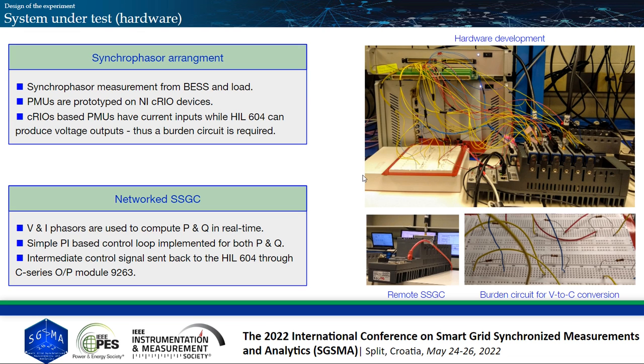So, we had synchrophasor measurement from PMUs, from battery energy storage system and the load. We had PMUs, which were essentially implemented on National Instrument Compact Trio devices. And the Typhoon HIL-604 produces low voltage real-time outputs of the monitored signals, which were connected to the